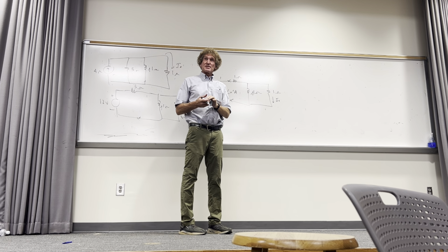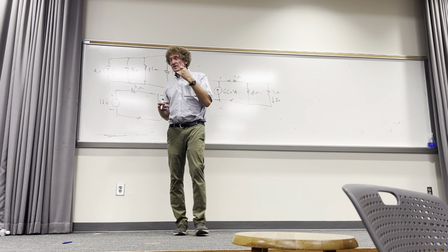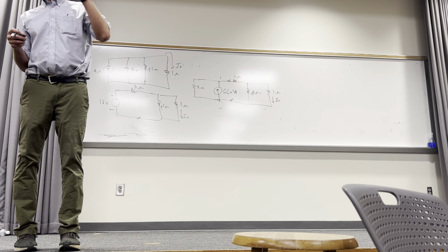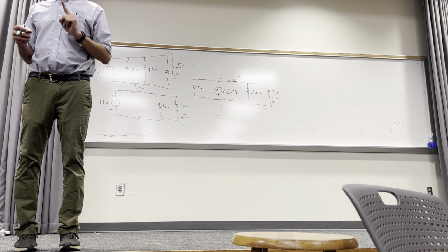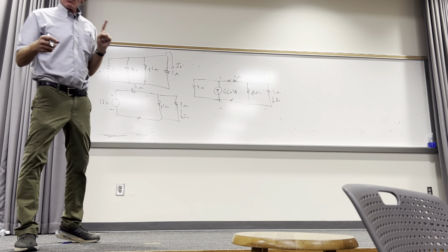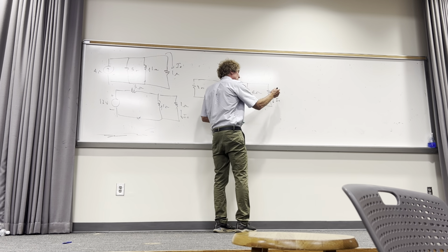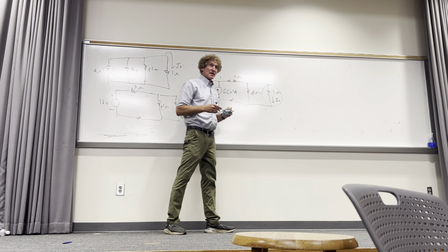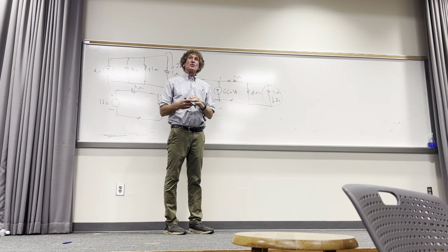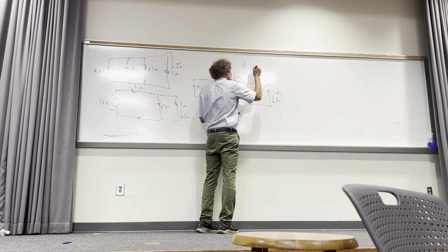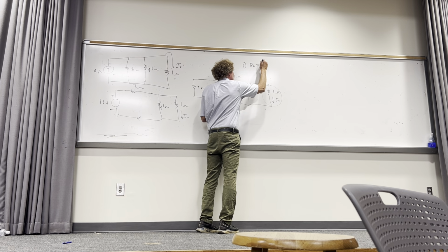So what is Thevenin's actual, I call it Thevenin's circuit analysis, but what's the first step in the process? First, you got to identify the load or the element you want the voltage or current through. You all see that's 1? Everybody. Then I'll label. I'll just put our load is 1 ohm.